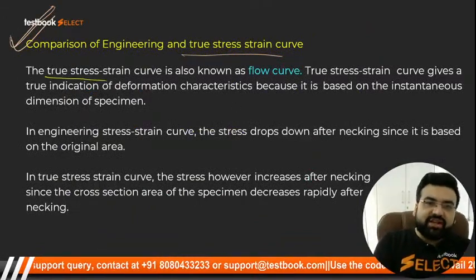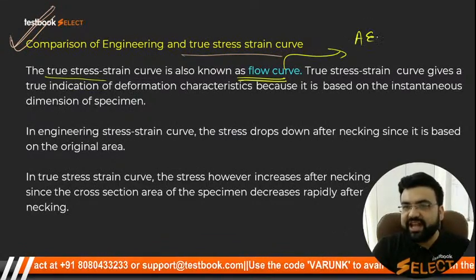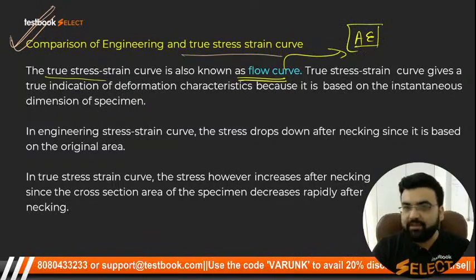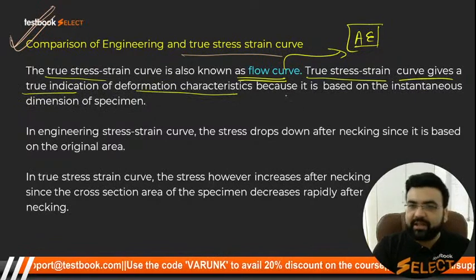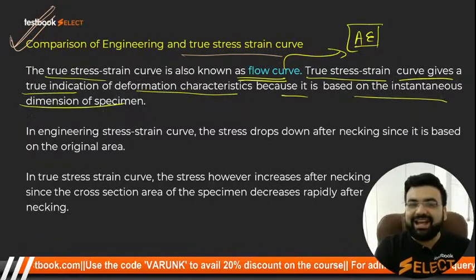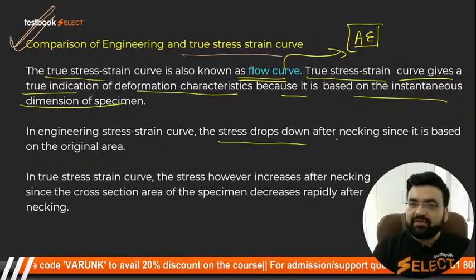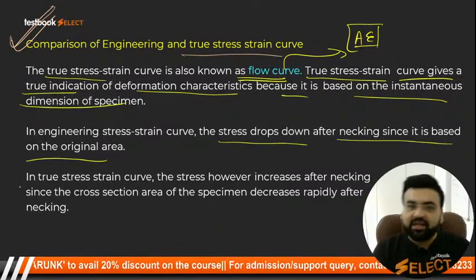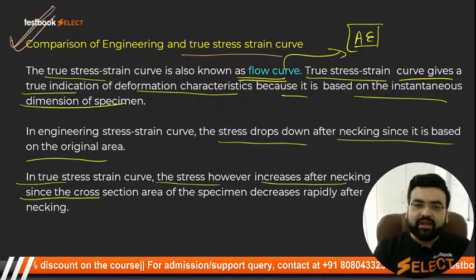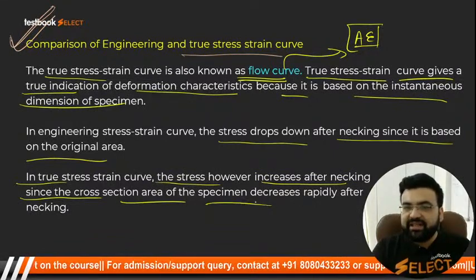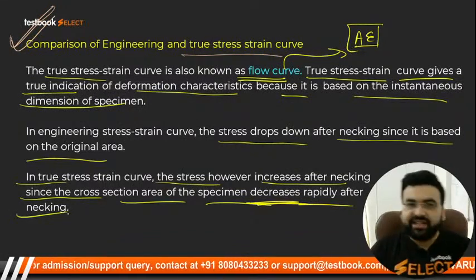The true stress strain curve is also called as the flow curve. This was a question recently in one of the state AE exam, but not GATE exam. True stress strain curve gives a true indication of deformation characteristic because it is based on the instantaneous dimension of the specimen. In engineering stress strain curve, stress drops down after necking since it is based on the original area. In true stress strain curve, the stress however increases after necking since the cross-section area of the specimen decreases rapidly after the necking, and hence the stress keeps on increasing after the necking.